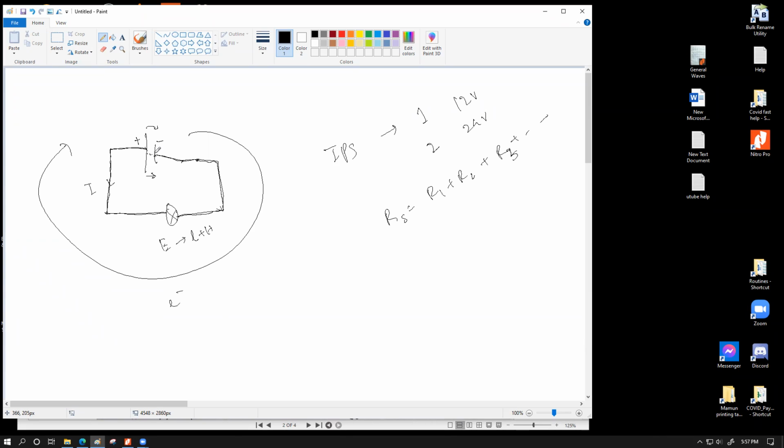So this is the basic theoretical idea for why internal resistance does exist. You just have to know why it exists. You don't have to remember all of this battery construction. I talked about this stuff to give you a concept of why this thing exists. The reason it was not introduced in your O levels is that it was a very primary level. We are basically skimming the surface of the electricity part, so you are given very simple formulas and mathematical orders. Now we're getting into a bit deeper situation, so that's why we're introducing the idea of internal resistance.